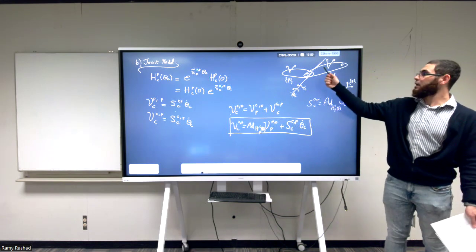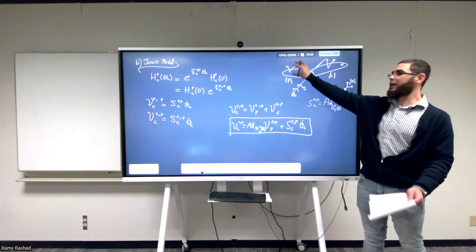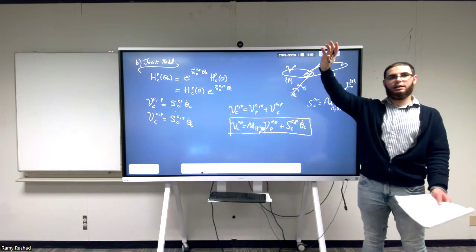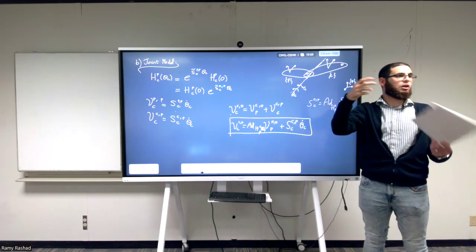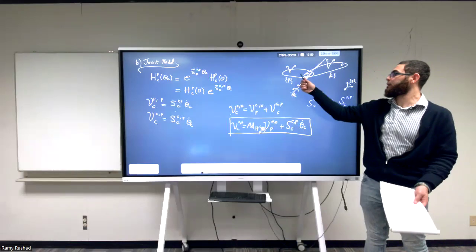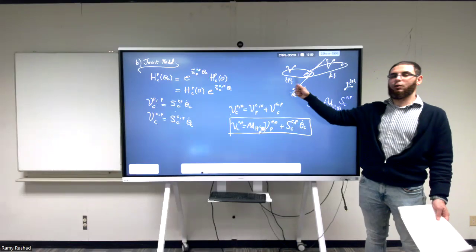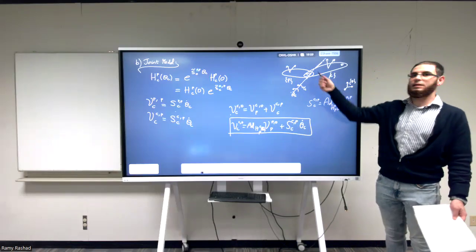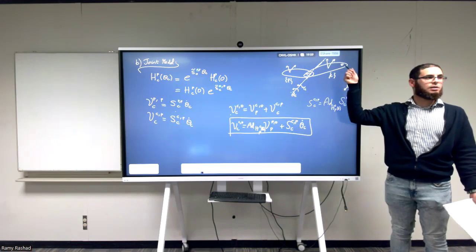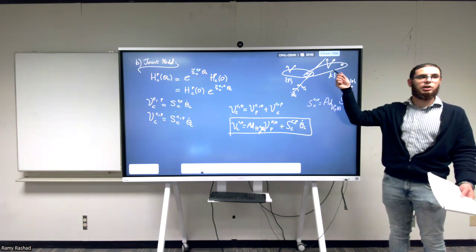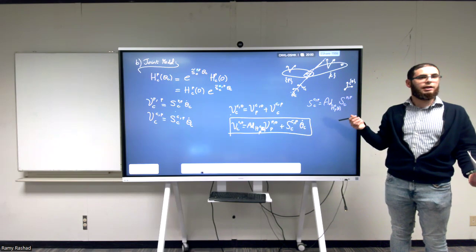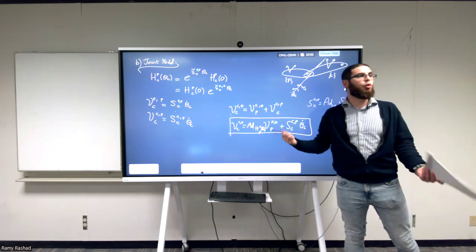Which means that if I say where the child is, where the parent is, or in other words, what the generalized velocity of it is at a certain moment, and then I also specify what the theta dot is, then the generalized twist of the child becomes identified. Right? There are no more degrees of freedom.